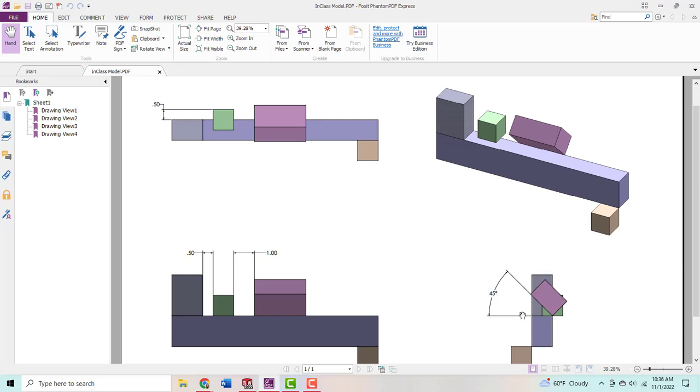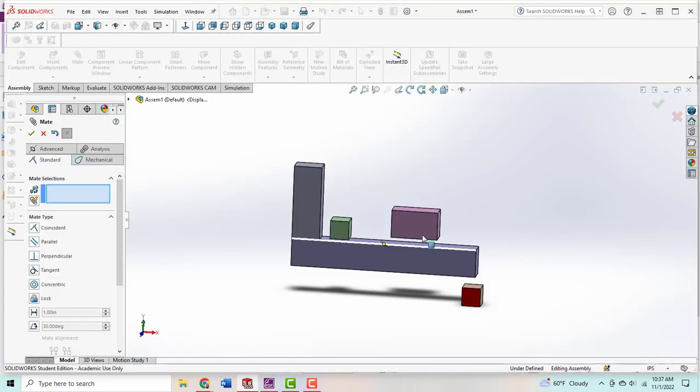We do have this 45-degree angle. So this is where it's going to be nice to just use an edge of our base component to create a mate, because we do want that hinge movement. Normally you want to use just the whole face and surface so you can prevent that, but in this case it is what we want to add in.